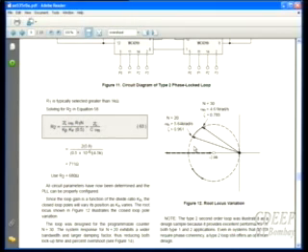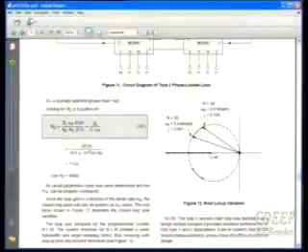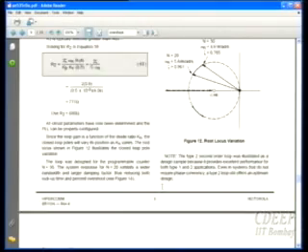They have designed for n equal to 30, maximum division ratio, therefore, which is zeta almost equal to 0.8, and then they get higher value of zeta for less value of n. So when you want to design, you use the maximum value of n because that will give you the maximum loop gain. That will give you the minimum value of zeta. And then when you reduce n, you will get less loop gain, therefore your zeta will increase and it will be stable. Therefore, design always will be based on n max, maximum divider ratio.